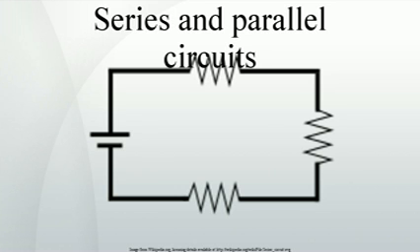For n equal resistors in parallel, the reciprocal sum expression simplifies to the following, and therefore to the next expression. To find the current in a component with resistance, use Ohm's law again. The components divide the current according to their reciprocal resistances, so, in the case of two resistors, the following holds. An old term for devices connected in parallel is multiple, such as a multiple connection for arc lamps.